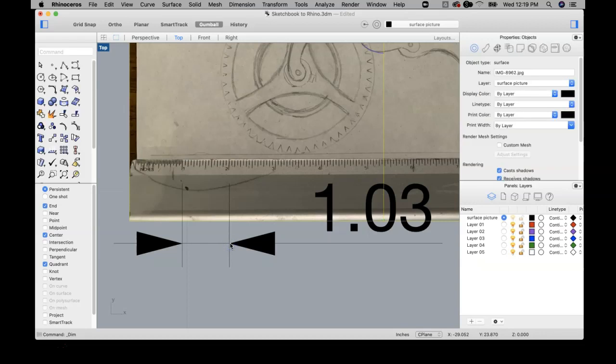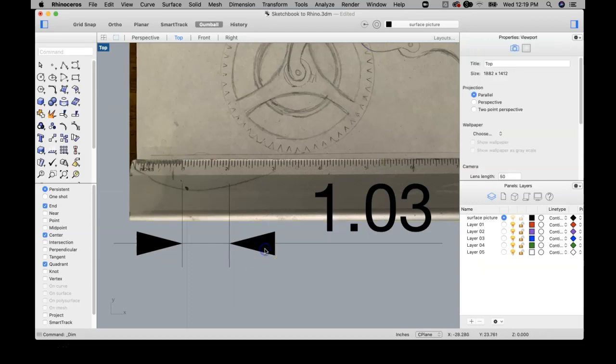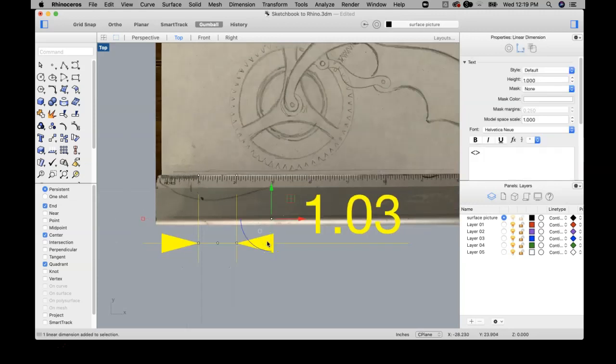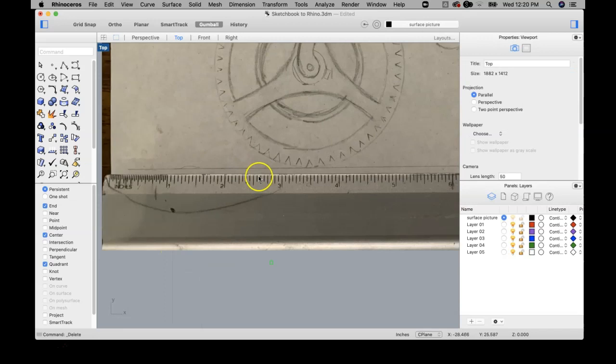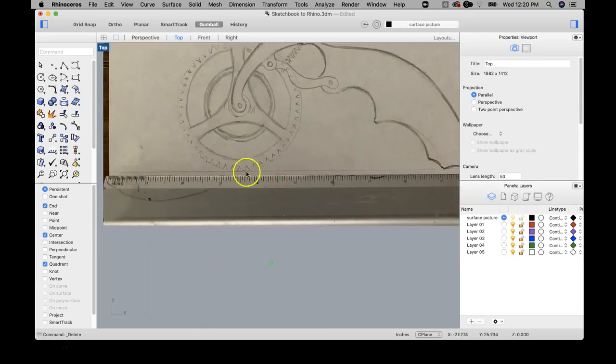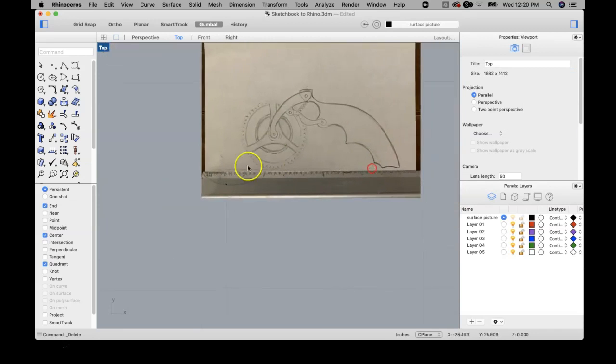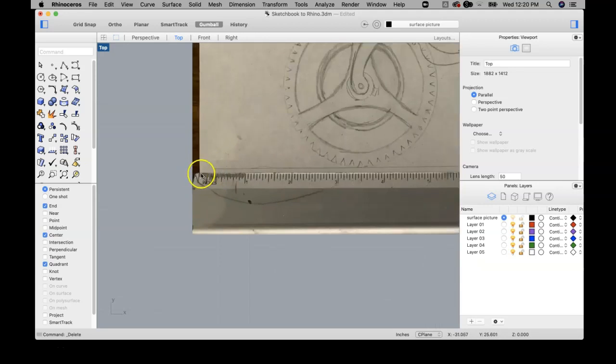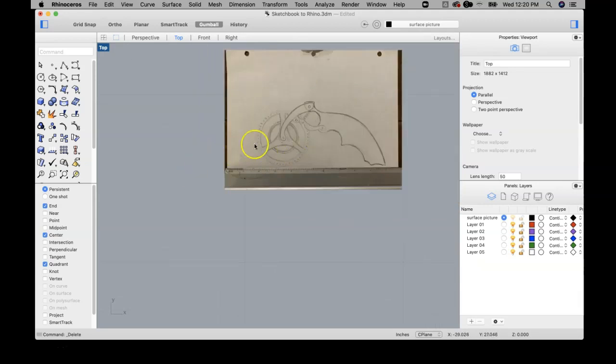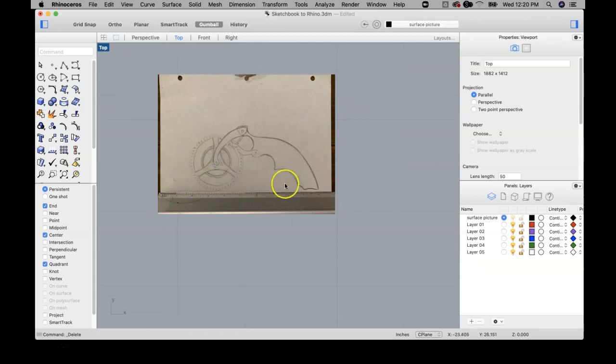So this is really accurate. And again, who knows how close I located those two points that I isolated there. But the longer the ruler, the longer that dimension, typically, you wouldn't want to scale it based on 1 inch. When we first scaled it, we'd probably want to scale it on as large of a surface as we can, and we'll have greater accuracy that way.